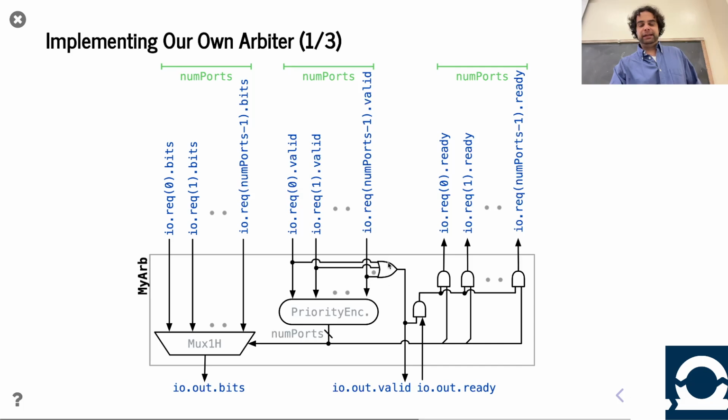And I manually drew some logic gates in here to try to show some scenarios, right? For example, if the output's not even ready, nobody's going to get anything because they're not going to win, right? It's a little bit unclear, but basically, this is an n-bit bus coming out of here, but it's one hot, and with one hot, it's nice because you send just one wire at a time to these AND gates, and then we can make this work. Basically, if your thing has been requested and the output's ready, it comes together. This OR gate here is seeing, are there any requests? If there's no requests, then nobody should be getting a ready signal or anything.